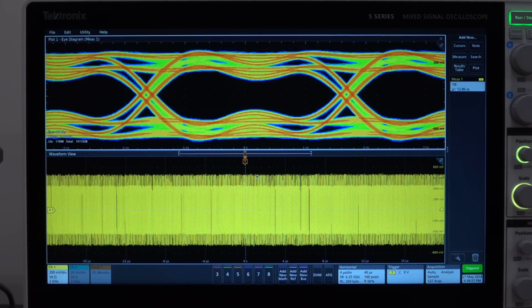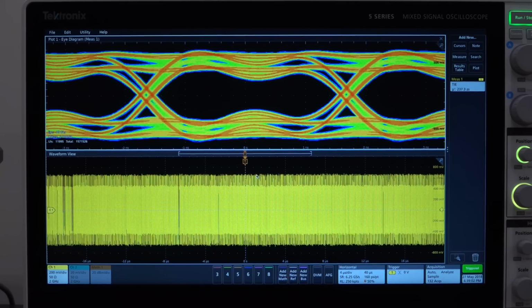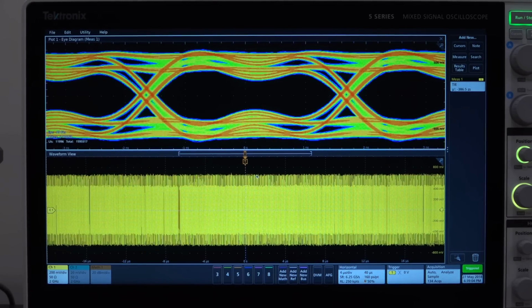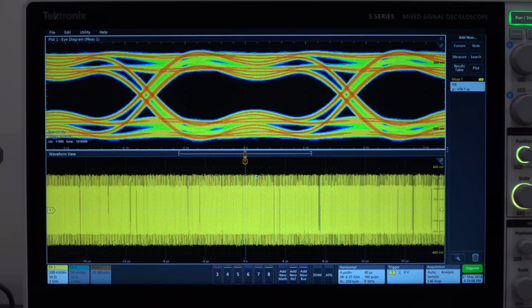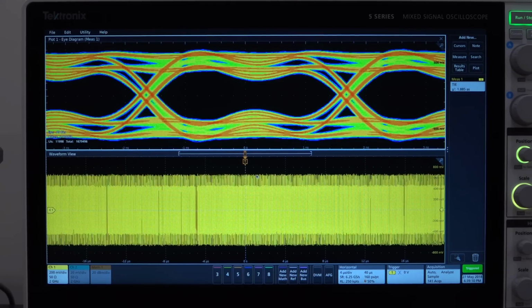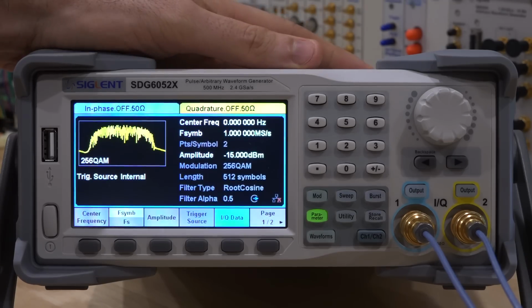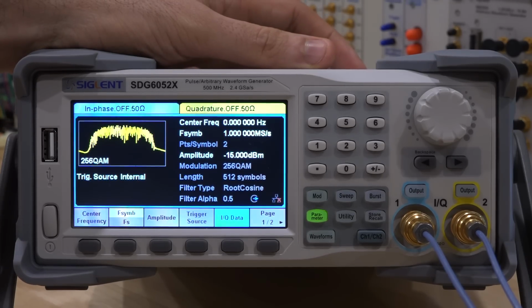Now, one of the other things this box is targeting is, of course, wireless communication, and it has a built-in IQ modulator, and I want to see how that behaves. And we're going to go back to the spectrum analyzer and see if we can create some complex modulation and how well it behaves under various situations. So when it comes to IQ generation, this instrument is intended to create complex modulation for primarily wireless applications.